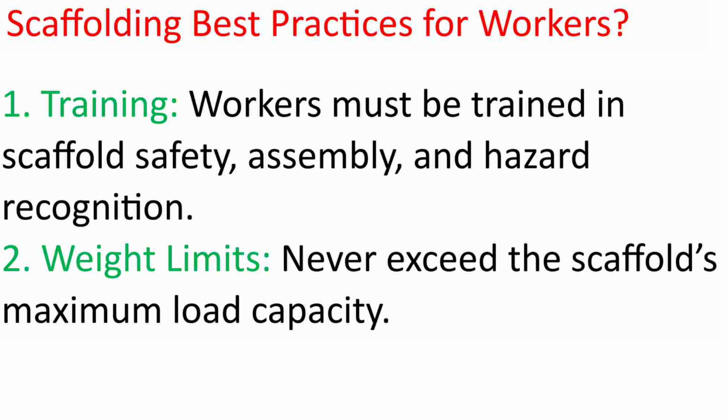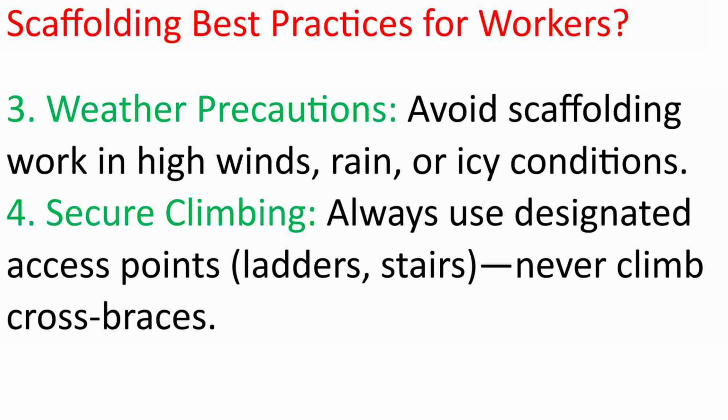Question: what is the scaffolding best practices for workers? 1. Training. Workers must be trained in scaffold safety, assembly, and hazard recognition. 2. Weight limits. Never exceed the scaffold's maximum load capacity. 3. Weather precautions. Avoid scaffolding work in high winds, rain, or icy conditions.